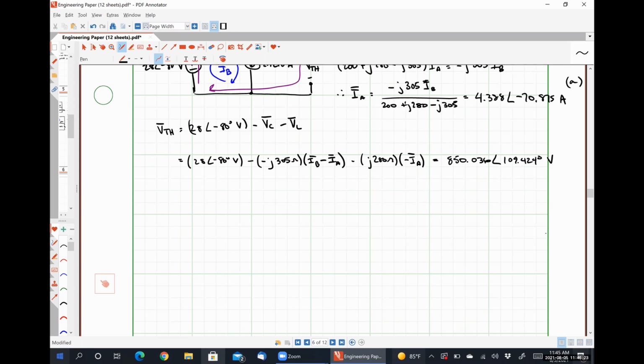So that would be one way to potentially do it. We'd have to do nodal analysis to figure out what that voltage is, and then do Kirchhoff's current law at the node where the resistor and the inductor are connected to figure out what the Norton current is. So it would be two steps there. Or we would wind up doing mesh analysis where there are 3 meshes that we'd have to take care of. Our other option is finding the Thevenin impedance directly and then using that to calculate the Norton current. And to me, that seems like a much easier thing to do.